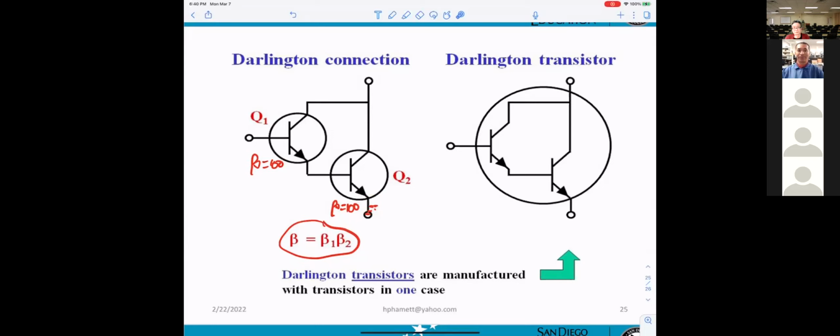So let me see if I understand what you're saying. You're saying don't take the negative lead of the scope or the DMM and touch the emitter. Exactly. So you can use the red lead, but not the black lead. Right. However, with the meter, if you're using both sides, do not connect the black to the ground. Sometimes you run into the problem. And also, lately, most people run into the problem when they're using the scope.